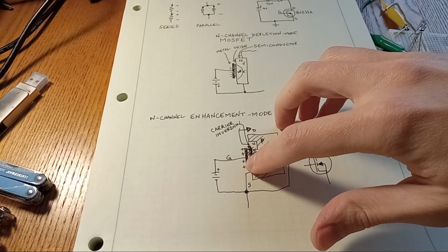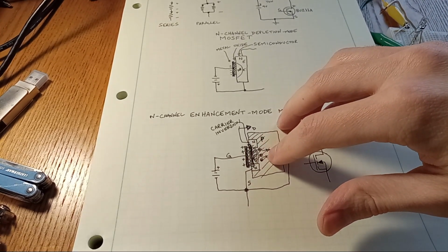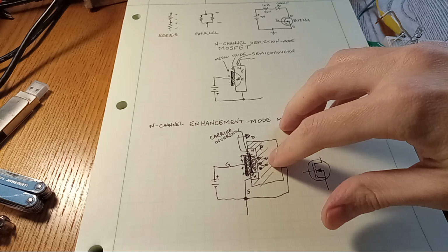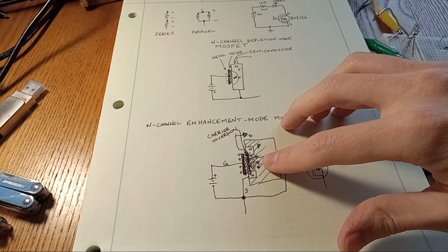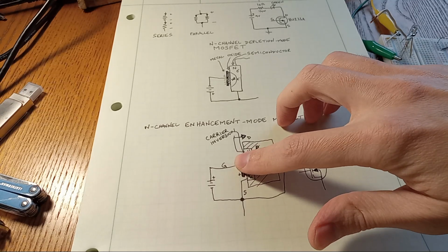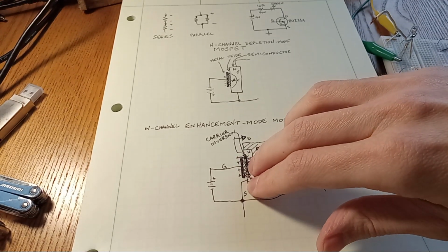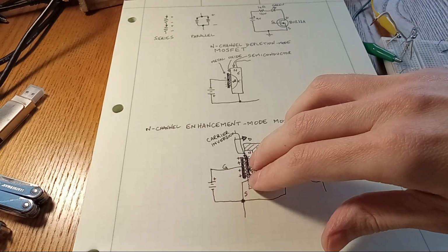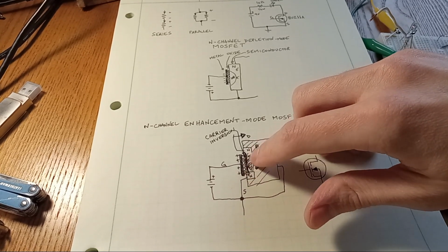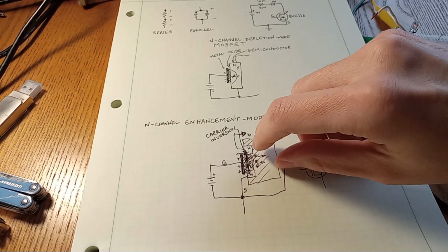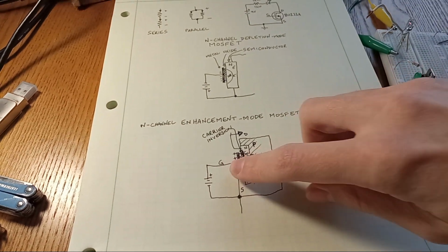Applying a positive charge here repels the holes away from the area under the gate and attracts minority carriers, electrons, which are still present in P-type silicon, converting a thin layer effectively to N-type, which creates a conductive channel between these two little islands, the thickness of which can be controlled by varying the gate voltage.